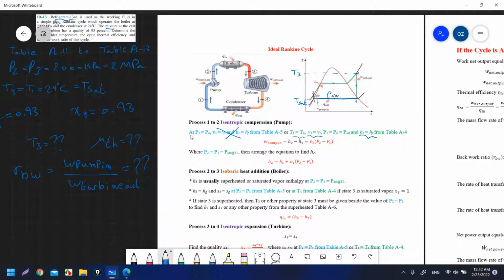So this one is Psat also if I want the pressure, and the constant pressure lines in the T-S diagram are like this. All of these have the value of Psat. Psat is equal to the pressure P1 and P4. This line represents the pressure P1, which is equal to P4. They are on the same constant pressure line. The line passes through 1 and 4, and it's also equal to Psat. Because it is inside the dome, we have the saturation pressure also. So I can get all of these v, h, and P from table A4 this time. Okay, and now that's the problem.